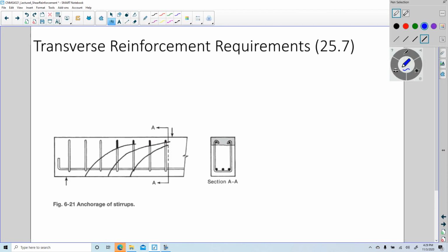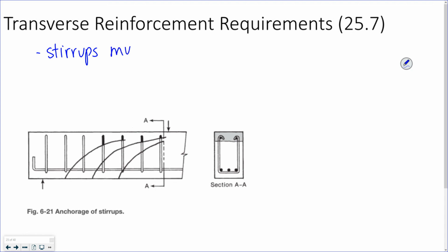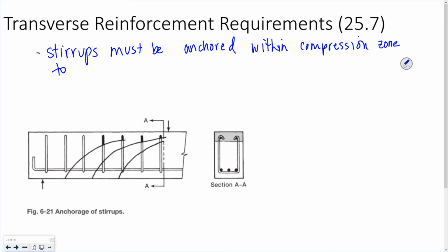So what I just wanted to write here was that they have to be anchored within the compression zone to develop their full yield strength. That means place as close as you can.